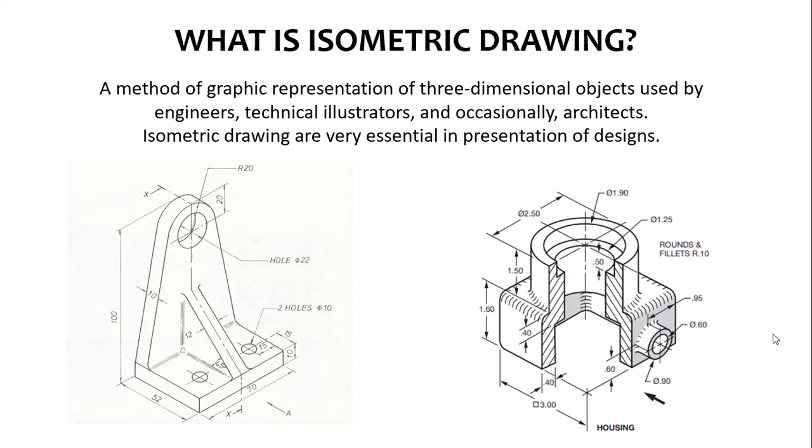Now, this isometric drawing does not show all the detail. For example, here they tell us we've got two holes. Of course, because they've said it's a hole, we know it's going to be a through hole. Another way of drawing, which is known as the orthographic, enables us to view just certain parts of our drawing.